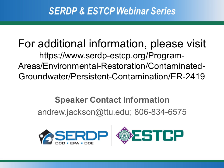Thank you. Is there any disturbance of the samples that might affect the results during the physical removal of the samplers following the equilibration period? Well, if by that the questioner means, is there an artifact of using the syringe to remove the water and then fill up the vial? Certainly there's a technique involved that you've got to be careful with, just like with any type of volatile sampling: you don't want to bubble a bunch of water into the sample, you want to stream it down the side, and you've got to make sure you don't get an air bubble.